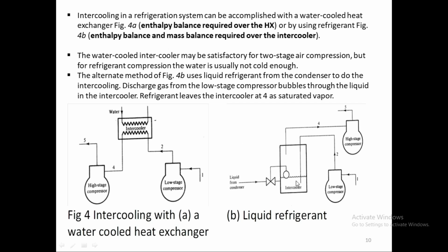liquid. So that way the liquid will stay here and the vapor which is coming from the low stage compressor will bubble out from here at a colder temperature. Okay, so that's the idea. So that colder vapor will go into the high stage compressor.